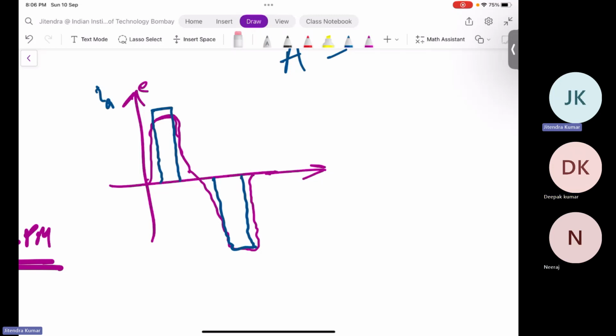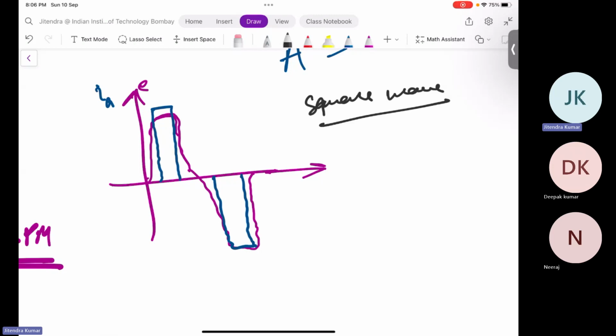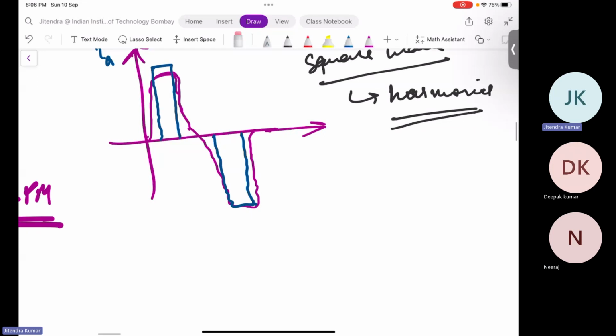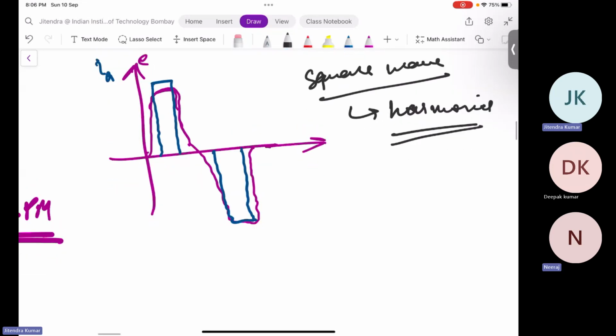You might not know this: as you use a square wave current, as you will also study in power electronics, it will have higher harmonics. Harmonics induce losses very significantly. Harmonics in current, magnetic flux and EMF lead to immense losses, and as you go to higher power, you will not be able to maintain high efficiency.